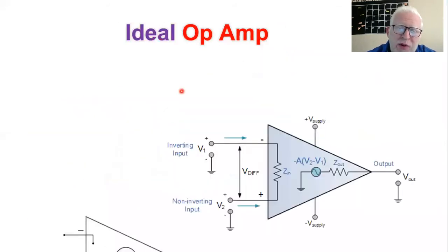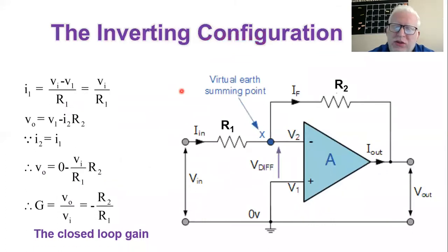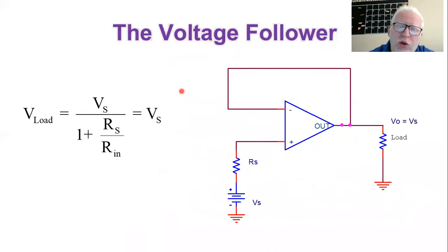In the previous part, we discussed two very important circuits. The first is the voltage follower, or the buffer circuit. This circuit is usually used to isolate the input source from the load so that you can carry the voltage without any loading effect. And we discussed in detail how this circuit works.